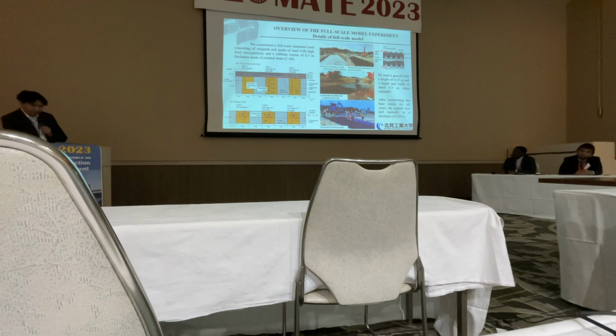The following photos are the full-scale simulated roads during construction. 2 layers of geocell material were backfilled with subgrade soil and compacted with hand guide rollers. Sand with high frost susceptibility was used for the subgrade soil in all 3 cases. Crushed stone C80 was used between the cases to separate each case, the gray one. The following figure shows the case 3 example configuration of the subbase course reinforcement method using geocell in this study.